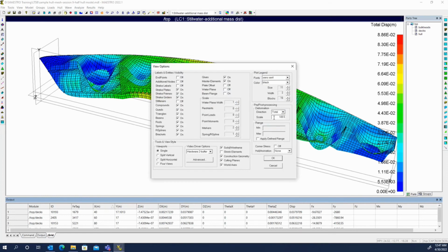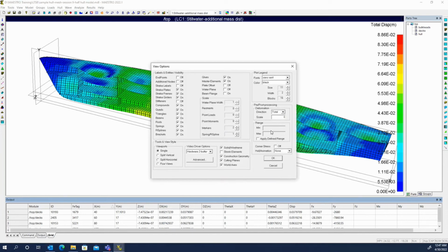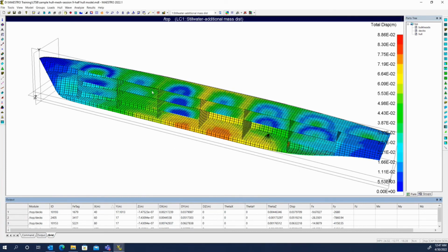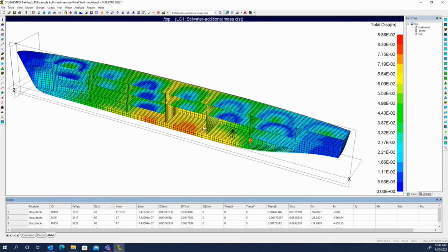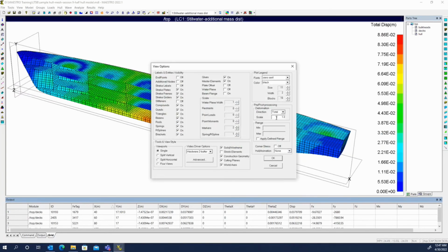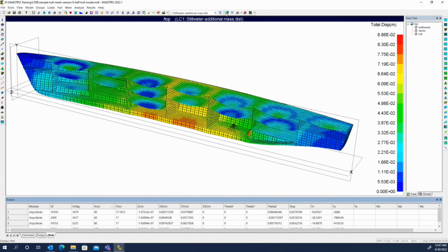And let's change the scale of the deformation. Now this won't change the scale of the coloring. So actually, if you wanted to see a color-coded, undeformed model, we could probably come in here and change the scale factor on the deformation to 0. So it's undeformed, but the colors indicate how much deformation there is in each area. Oh, I'm sorry, it won't allow 0. So scale factor of 1. Okay, so yeah. And if we bump this up to, say, 25, you can see sort of the deformed model with the color coding.